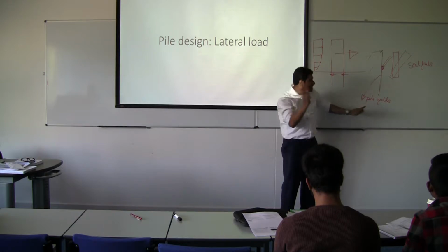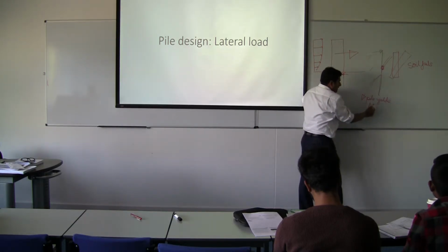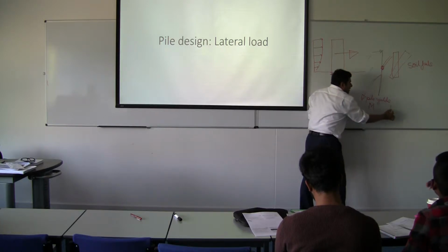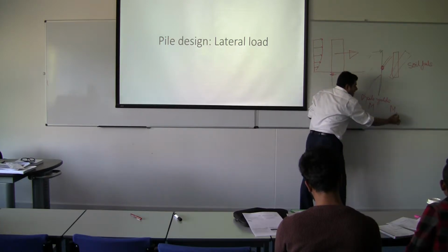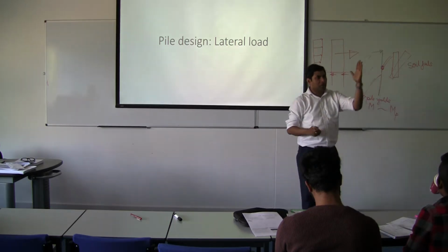Yes, so you will calculate the moment applied by the load, and you will compare with plastic capacity, MP. Right? This is what I mean.